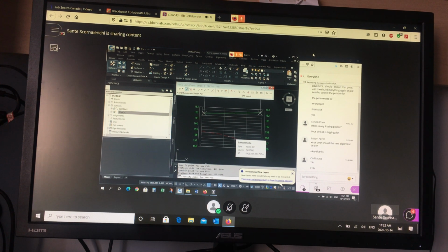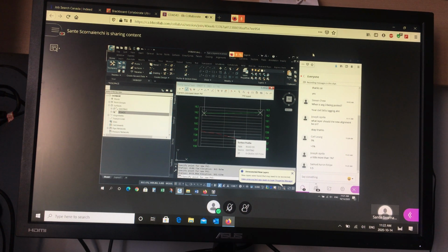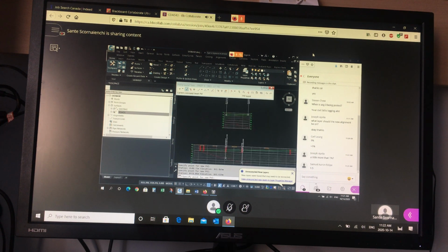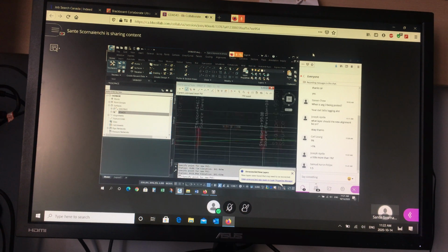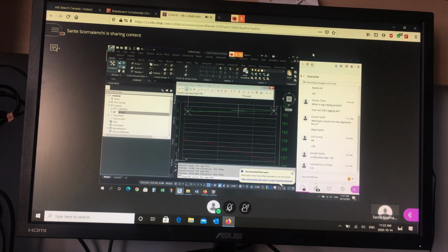What do you think the gutter slope's going to be? It's going to be greater than 1%. A little more. Yes, exactly. Awesome. Everybody's thinking. It's going to be a little more than 1%. Why? Because when I designed this to be 1.5%, I rounded it up, which means the gutter will be at least 1%. So this should be, by no surprise, at least 1%, a little bit steeper than 1%. And when you see that, you shouldn't be surprised. It should be what you expect.